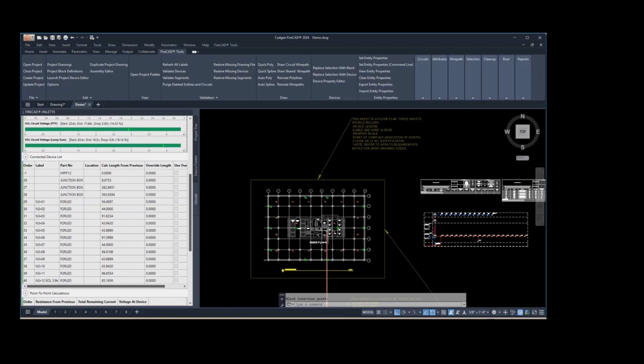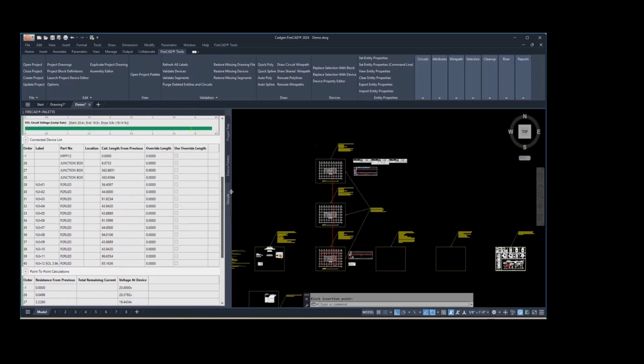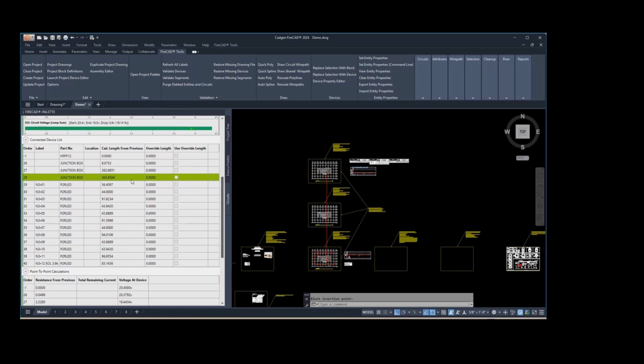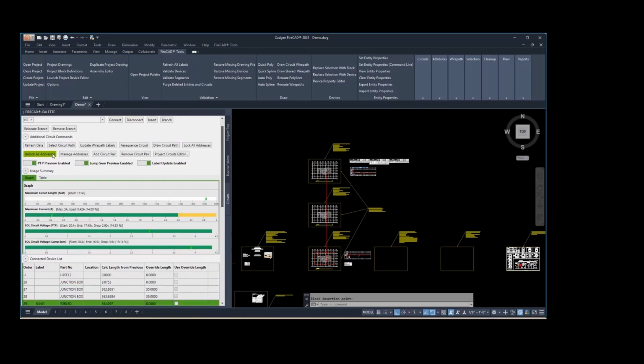That's because we're measuring AutoCAD distance when we go from this floor to this floor. We need to correct that because it's really not that distance. It's more like 35. So I go here and I say, let's override these 360 some feet distances and replace those with, let's say, 35 and 35, because we want an accurate voltage drop calculation, point-to-point voltage drop. So then I just go up here and refresh data.